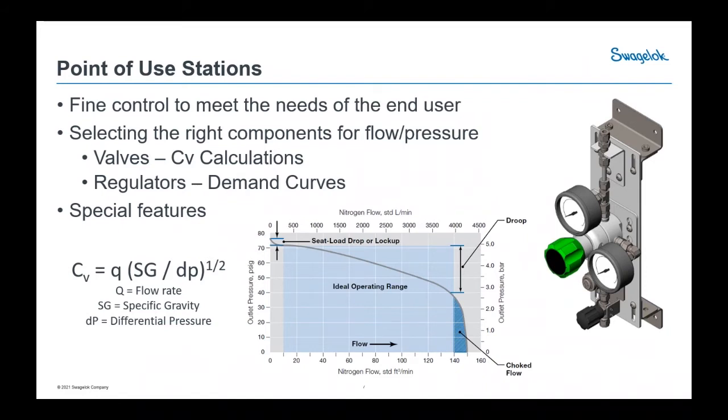So in terms of your flow control, looking at valves initially, you want to make sure your CV of your valve is properly sized. So your CV is your flow coefficient. And that's going to be dependent on the flow rate in your system as well as your media. So it's important to consider what requirements your system has. And if you need help calculating that, Swagelok.com's got a really nice, easy to use calculator, so I recommend just checking that out on the webpage.